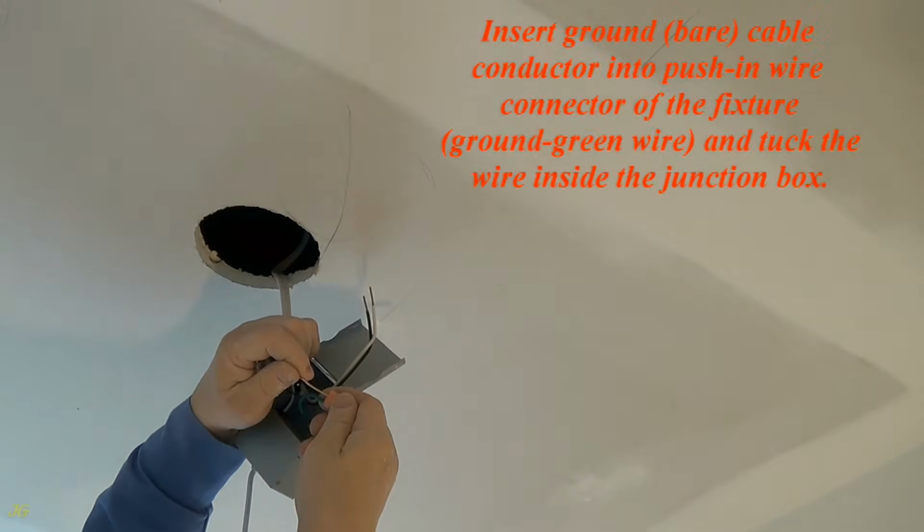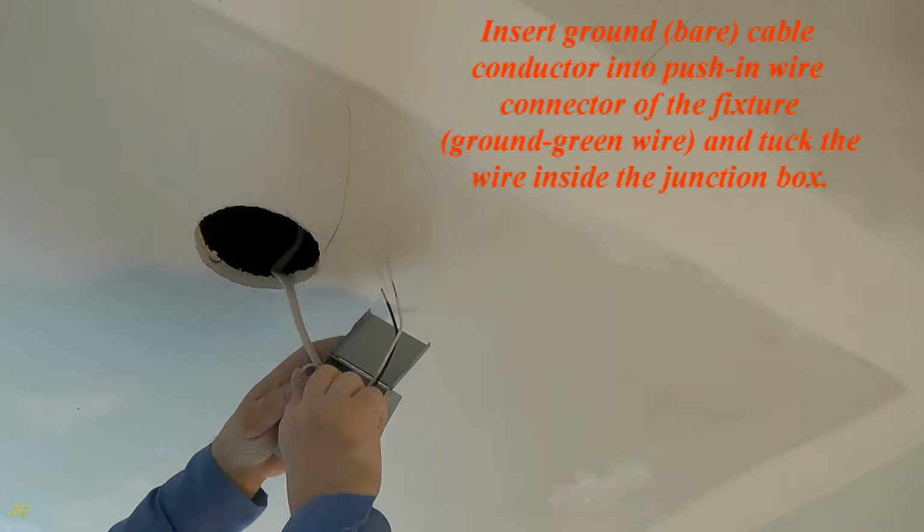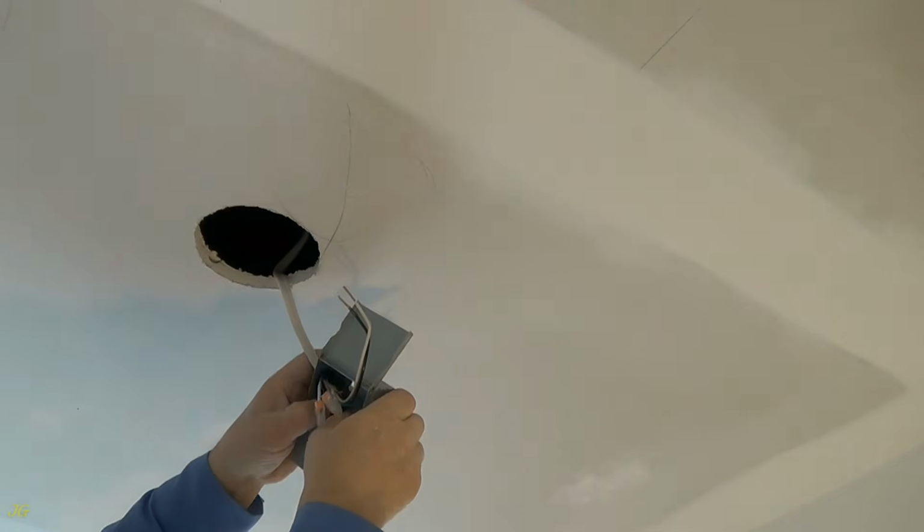Insert the ground, bare cable conductor into the push-in wire connector of the fixture, ground green wire, and tuck the wire inside the junction box.